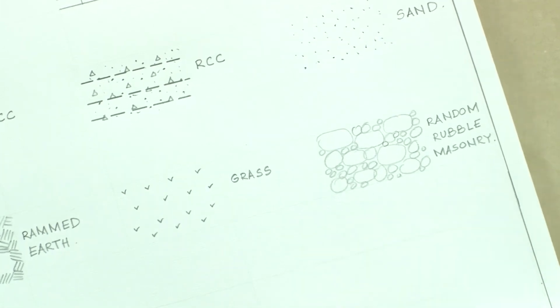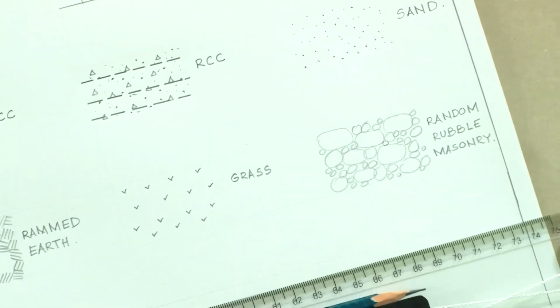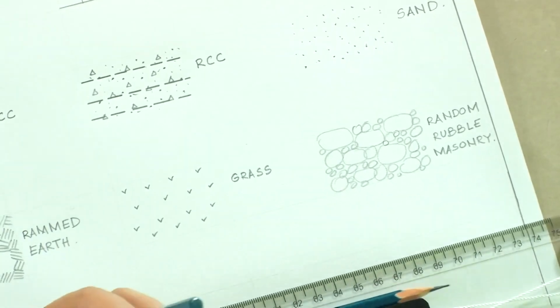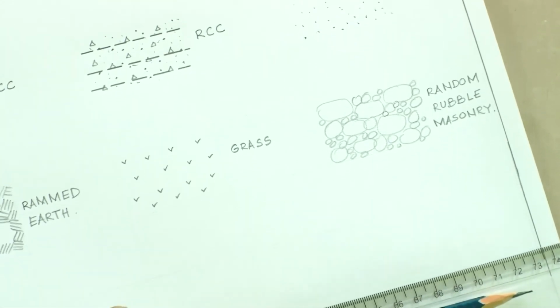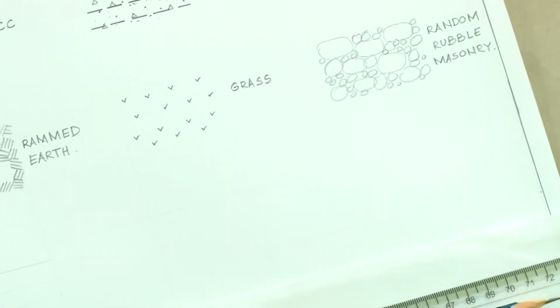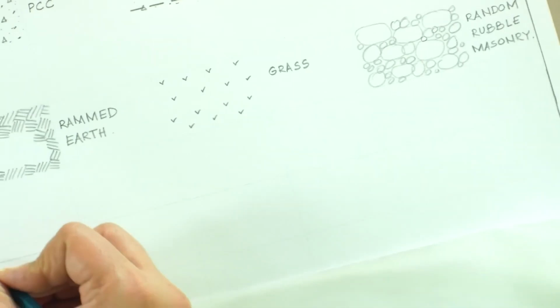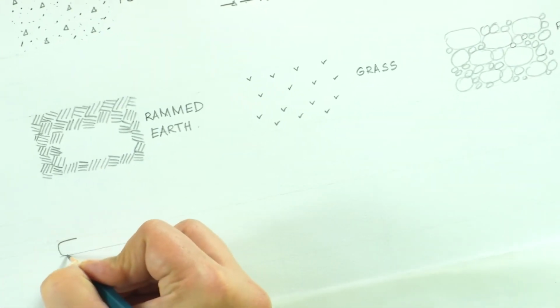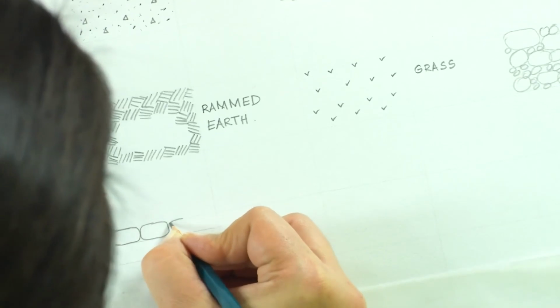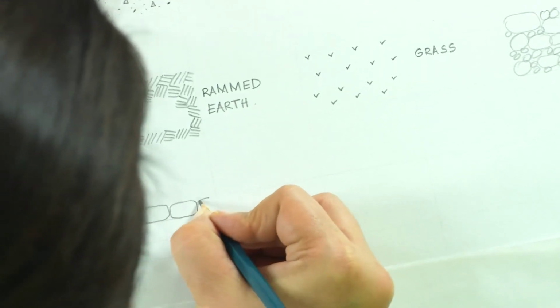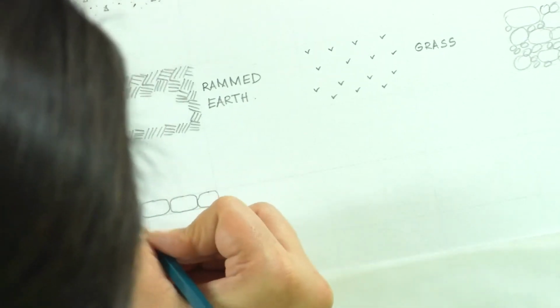We also have a dressed stone masonry. Dressed stone masonry is, if you see the forts from Rajasthan, you would see that they use it. You will draw very thin guidelines, and then within them we will draw these freehand representations for dressed stone.